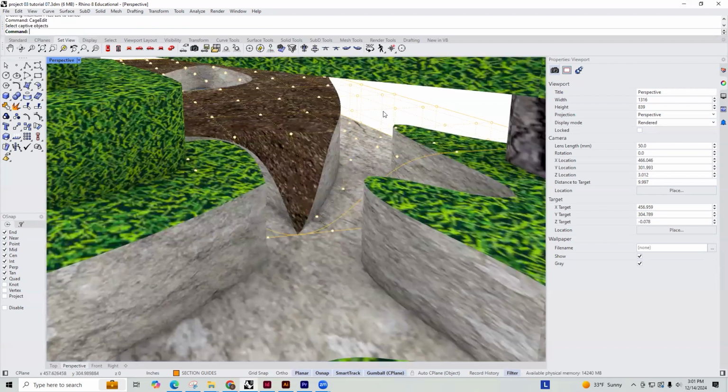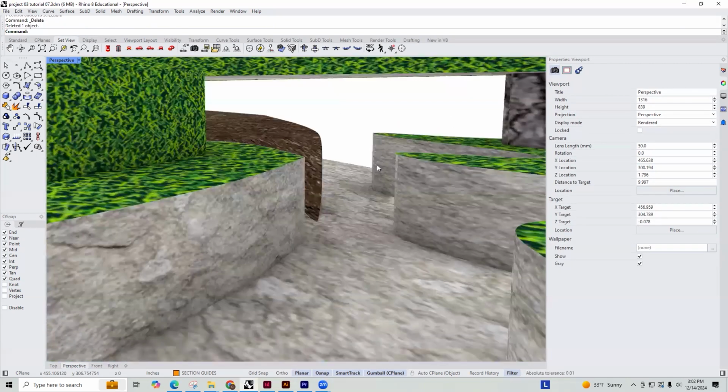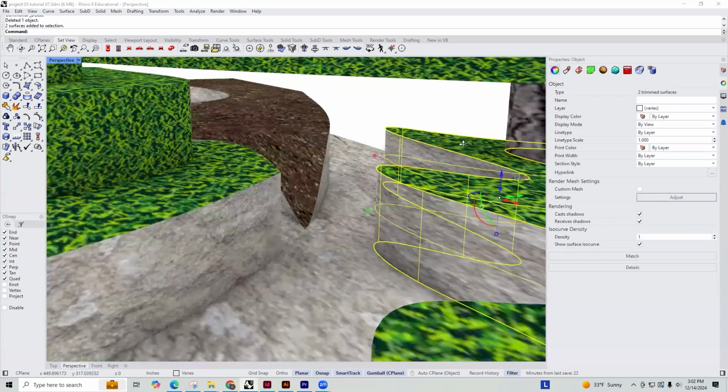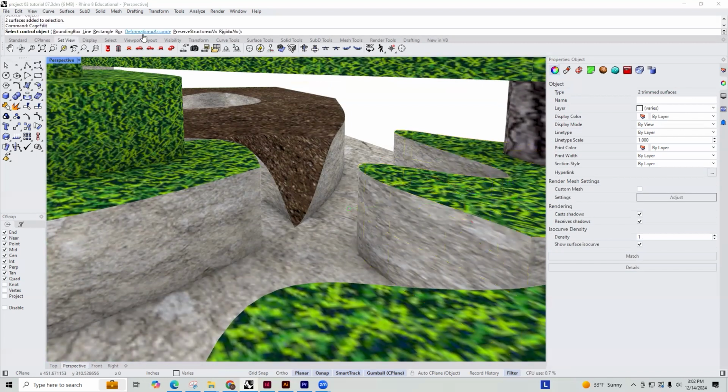All right. And again, this is something that's not required. That's why it's extra credit. But if you find yourself wanting to really get into different ways of manipulation, that Cage Edit tool really helps. So again, I clicked Cage Edit, Bounding Box, World. I have a lot of X and Y points. I'm going to reduce that to 8. I still only want to keep 2 points for the height.